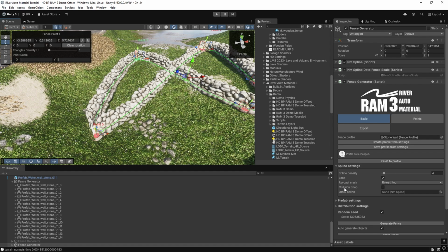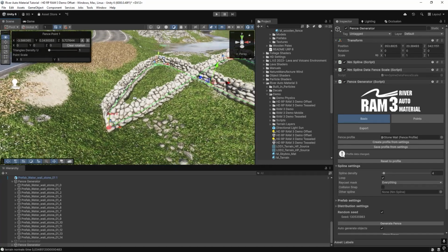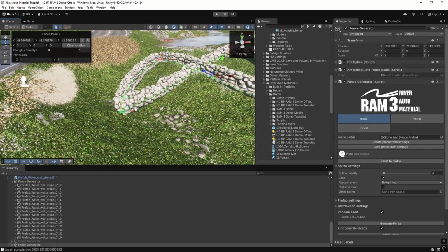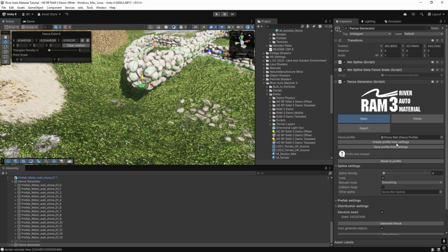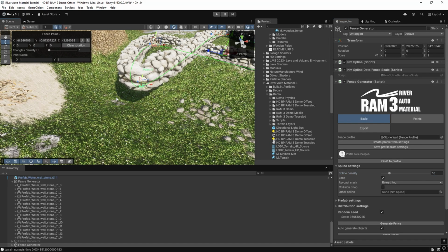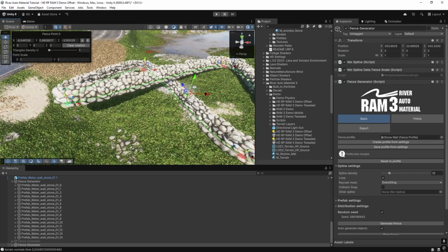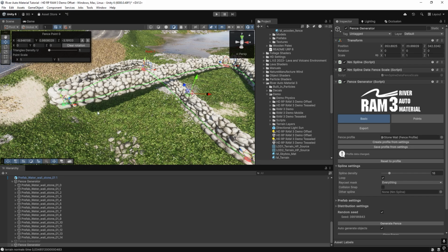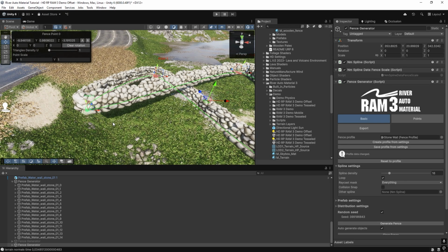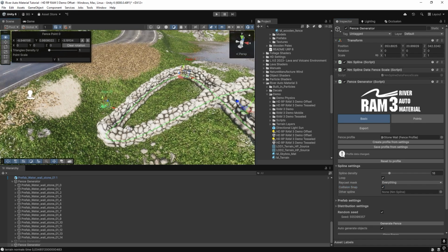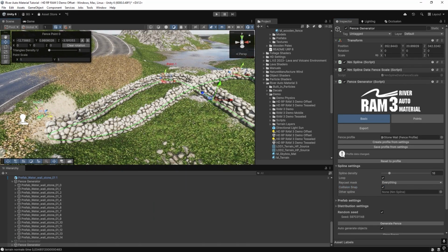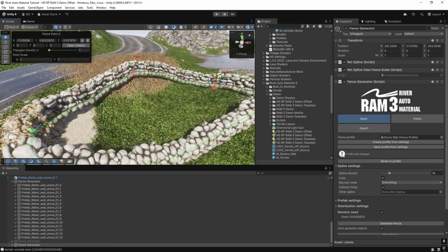We have also collision snap. You choose layer or layers for collision detection. It's cool because if you place a point very high, let's maybe increase the spline density very high, but you want to, for example, follow the terrain curvature, you don't have to place multiple points between points just to adjust it to terrain. You just click snap, and this object automatically gets snapped to the terrain, and it gets proper.